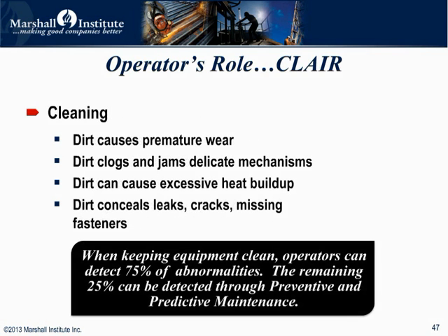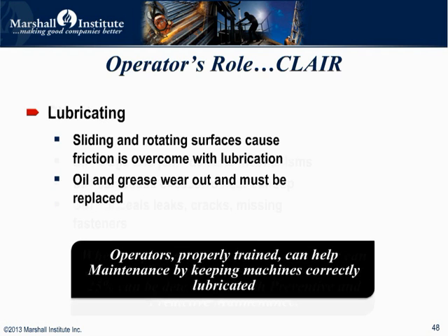So remember CLARE. Cleaning. Dirt and contamination are the enemy of maintenance. It's been shown that operators, just by keeping equipment clean, can detect 75% of impending failures. Lubrication. Lubrication is the foundation of preventive maintenance, and it can often be done as an operator task.